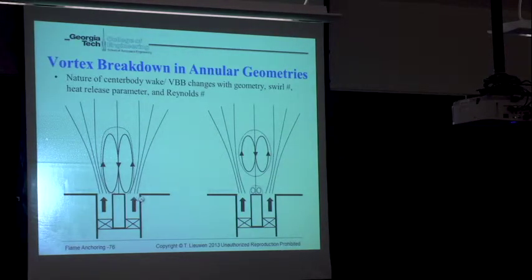Okay? The bottom line is that this is probably a lot more fluid mechanics than many of you may have ever wanted to get into. The conditions under which you can get a flame that's just floating out there, who's working on a low swirl burner? There you go. The conditions under which you can get the flame floating out there require a situation where you have high velocity, which is not going to allow the flame to flash back, but also a low velocity region where the flame can stabilize. So this type of geometry would potentially enable a flame that's floating out there.